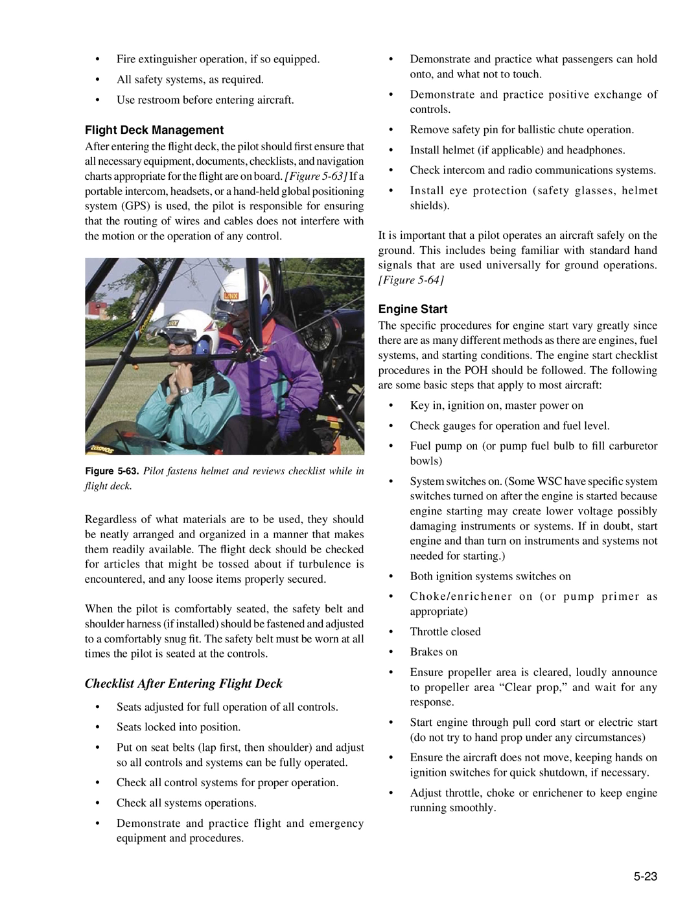The flight deck should be checked for articles that might be tossed about if turbulence is encountered, and any loose items properly secured. When the pilot is comfortably seated, the safety belt and shoulder harness, if installed, should be fastened and adjusted to a comfortably snug fit. The safety belt must be worn at all times the pilot is seated at the controls.